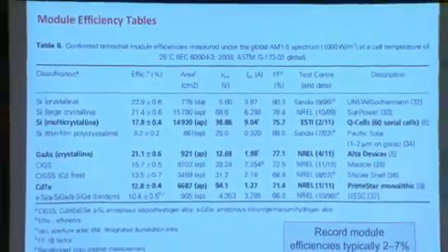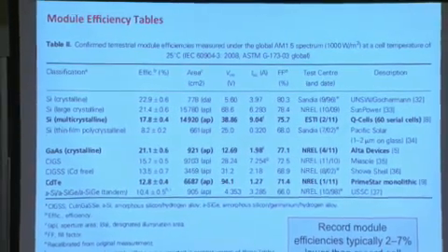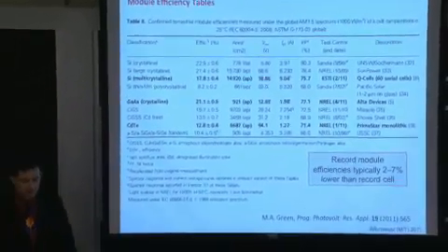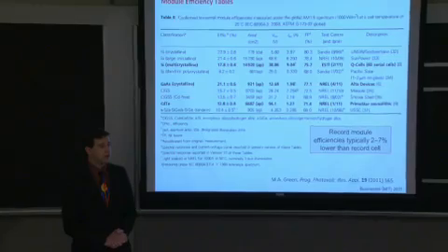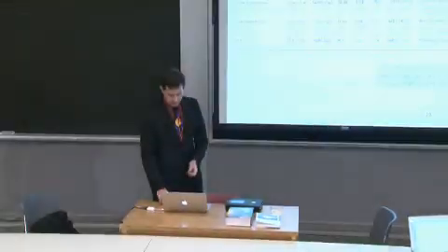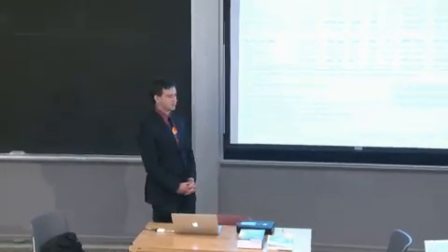You have a mix of cells that are different. Yep, you have a mix of different performers, and when you connect them in series and in parallel, you're going to be limited by the lowest voltage or current, respectively. Did I get that right? Yes. Okay. So certainly there are mismatches between the individual devices inside of a module.